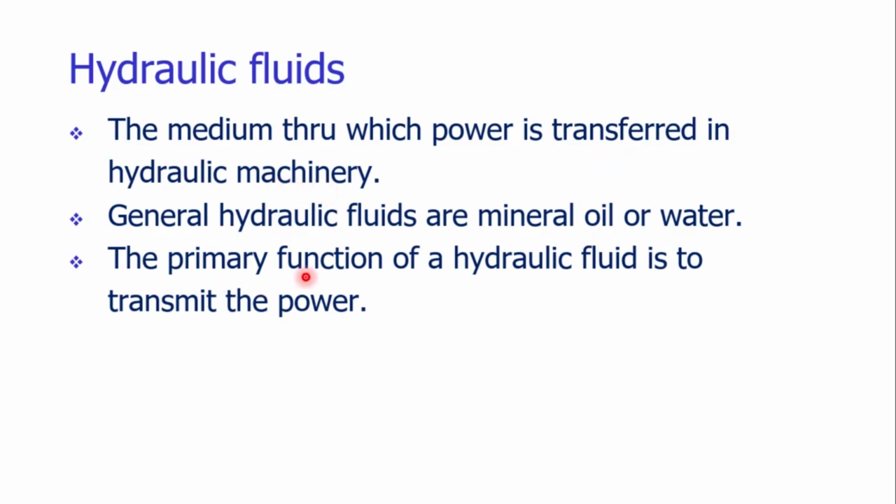In general, water is the best hydraulic fluid, but the flash point of the water is very low. It will get evaporated at a comparatively low temperature. Due to the friction inside the system, pressure may increase, the temperature will also increase, and that may lead to the boiling of the water, which leads to the cavitation problem and the failure of the device itself.